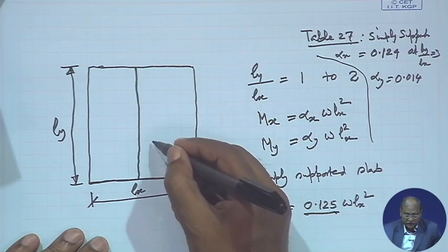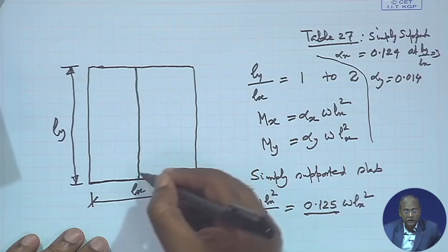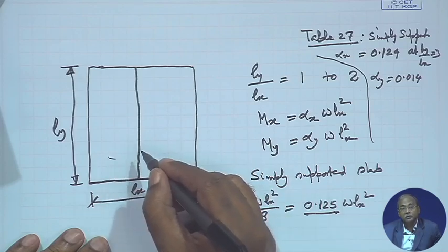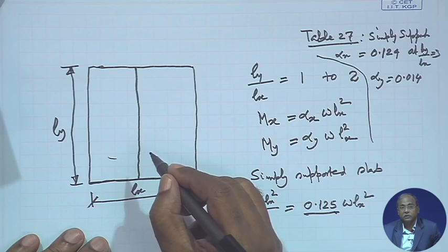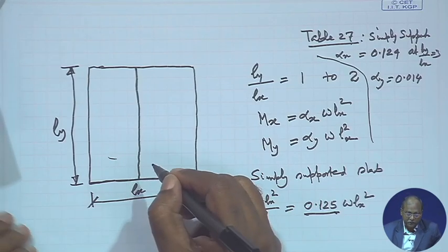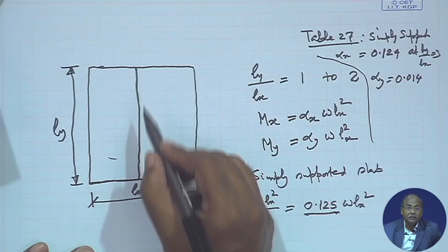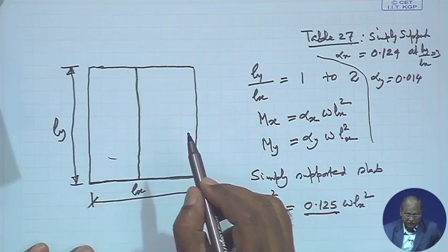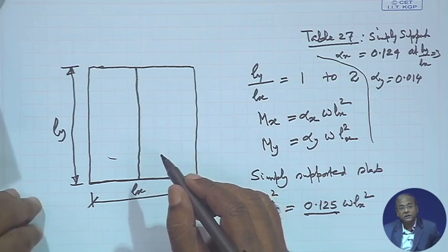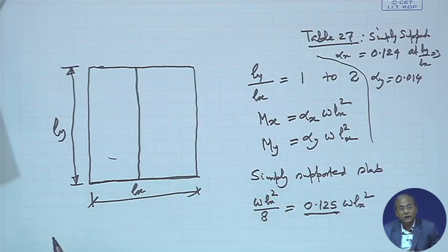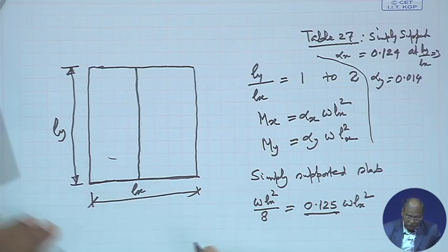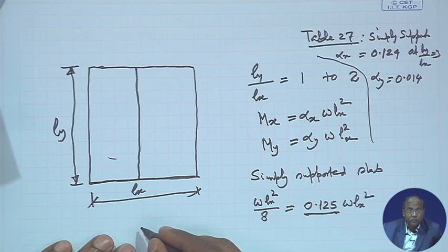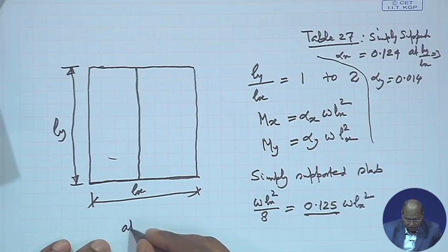If we divide it, your span will be reduced and your slab depth will be within the limit of 125 millimeter. So this way the beam will take care of the thickness of the slab. The next question is, where shall we provide the column? Generally, we provide columns at beam junctions.